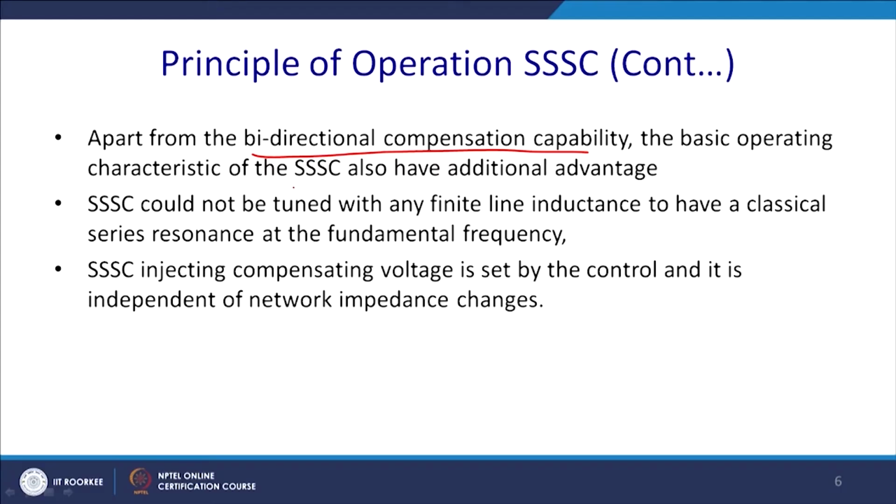So what we can conclude from this discussion? Apart from the bidirectional compensation capability, the basic operation characteristics of SSC also have some additional advantages. SSC should not be tuned to any finite line inductance to have a classical series resonance at a fundamental frequency.